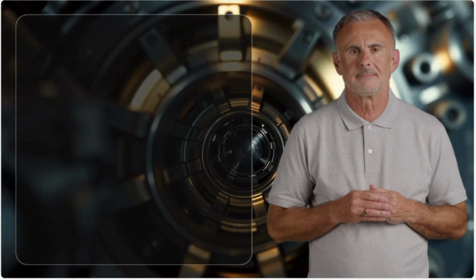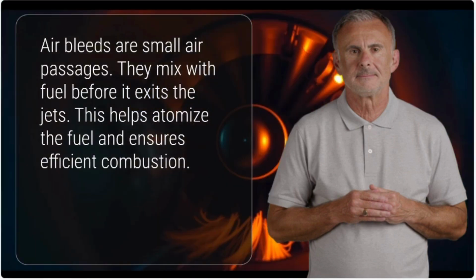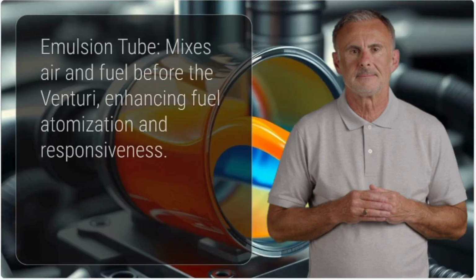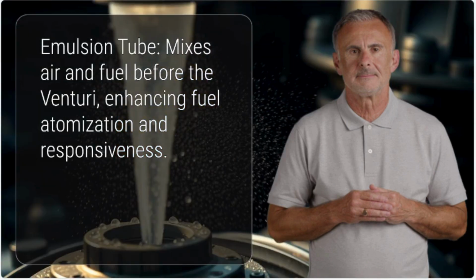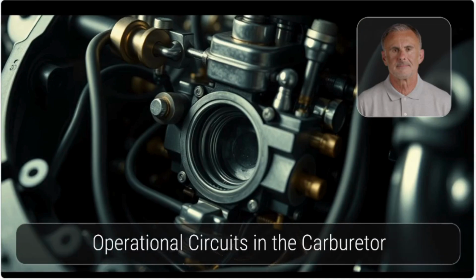Air bleeds: small air passages that mix with fuel before it exits the jets, helping to atomize the fuel and ensure efficient combustion. Emulsion tube: in some designs, mixes air and fuel before the mixture reaches the venturi, enhancing fuel atomization and responsiveness.